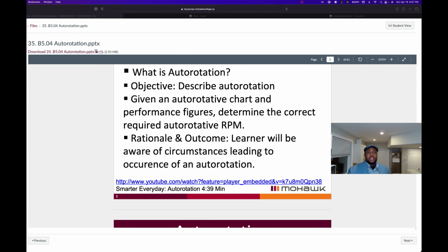During autorotation, the opposite is true, and this airflow moves up through the rotor disc. When these blades rotate, they effectively form a disc. During powered flight, the direction of airflow is down through this rotor system onto the body of the helicopter. During autorotation, the helicopter is falling down and the air is flowing up through. And this is what we term autorotation.